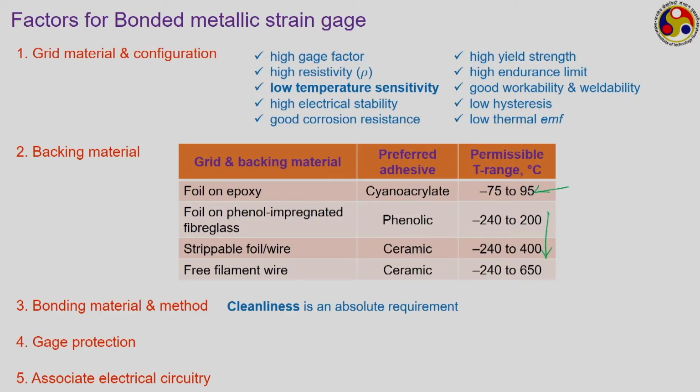Like in a bridge circuit, normally the output voltage is 0, and whenever there is a change in resistance in any of the arms of the bridge, then there will be a change in the output voltage, or some output voltage we are going to get. Now, you have to sense that output voltage using some kind of suitable voltage measuring instrument, and depending upon the nature of the instrument that you are using, the effectiveness of the strain gauge keeps on changing quite a lot. So, we need to discuss a bit more about possible kinds of electrical circuits.